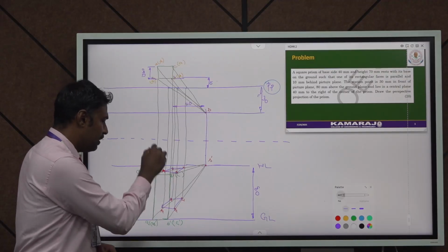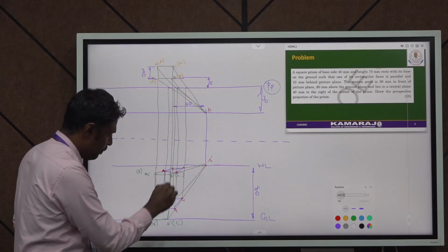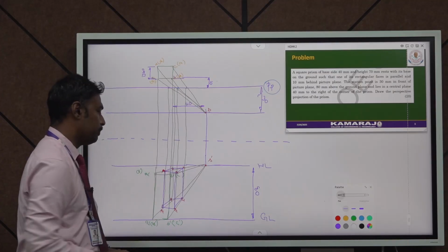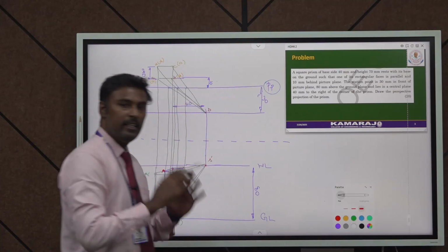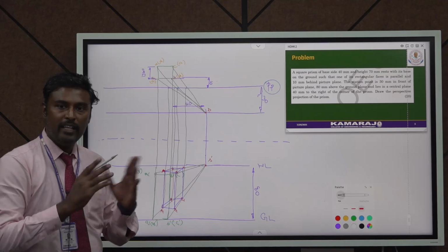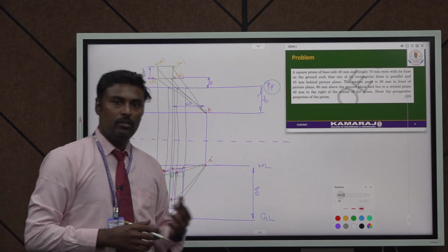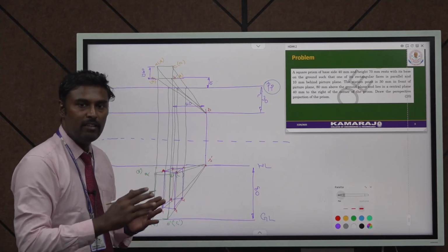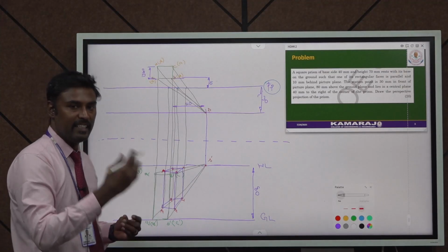Now it's our duty to connect all these lines, that is the rectangular faces, that is A to A1, B to B1, and C to C1, and D to D1. So finally we are going to get the final output. If you connect all these 4 edges, the final view should represent only thick visible lines. So you have to take your H pencil, and the final outcome of the perspective projection 3-dimensional drawing should be highlighted with thick lines.